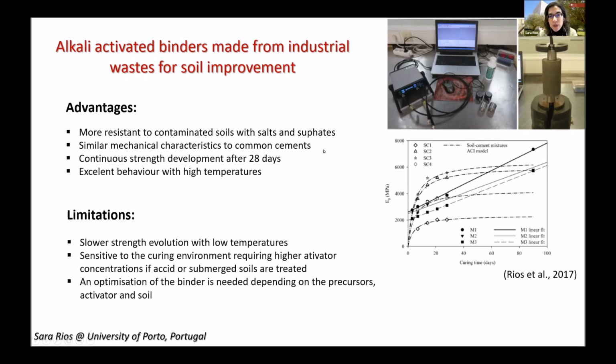But of course, if we use it in submerged conditions, for example, deep soil mixing columns in a coastal environment, in that case, we will require a high concentration of activator. So what we realize is that these binders still need an optimization regarding the type of precursor, the type of activator, and the type of soil that we are using.